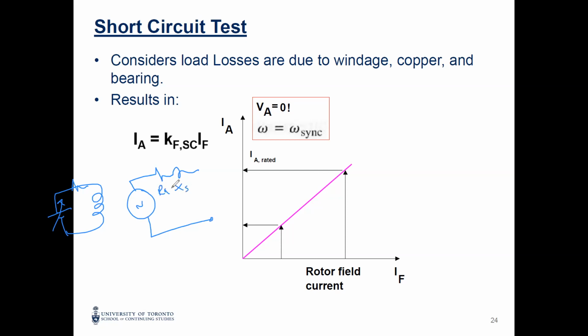But with this, we are going to have a short circuit, or we can add a meter. As you may know, the ammeter has a very small resistance, the opposite of the voltmeter. So in case you put your ammeter, it's as if you put a short circuit. So you are going to measure the current, but it's as if it's a short circuit.